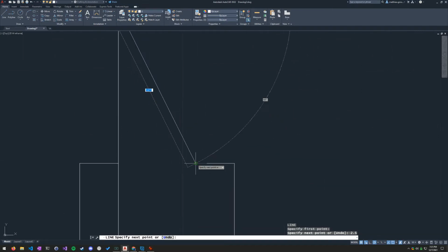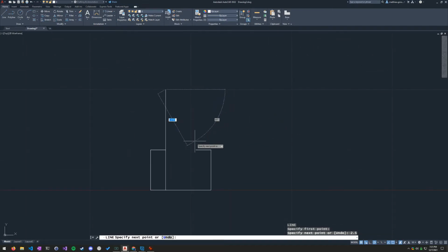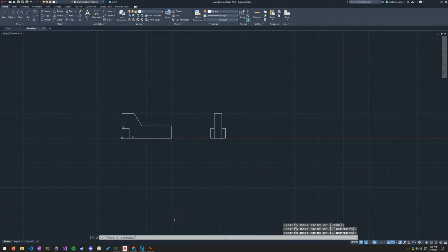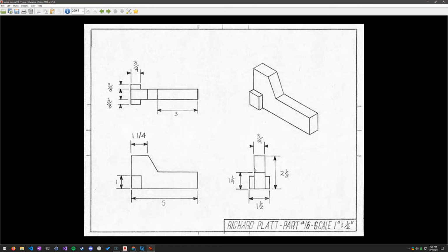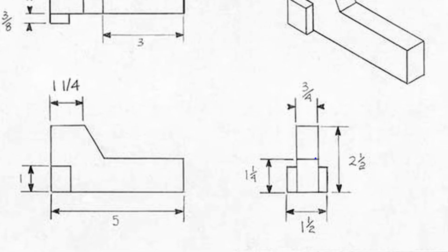But I could also track from here since I know that that's right. So I'll put my mouse here and track up. Click. Track all the way down. Click. Enter to close the line tool. So now we just need one more thing. And that's this line here. And this line is just this line. That's what that line represents.